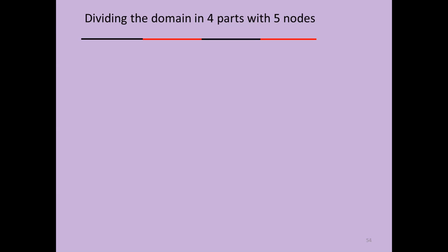But supposing if this was a 2-dimensional domain, that is a rectangle, let's say, or a square, let's say, then the length of the divisions along the x and along the y need not be the same. So we have the first node at x is equal to 0. U obviously represents the deformation. So since we are talking about the first node, the unknown is going to be represented by U1, that is deformation at the first node.